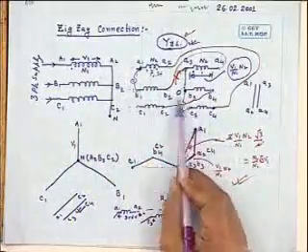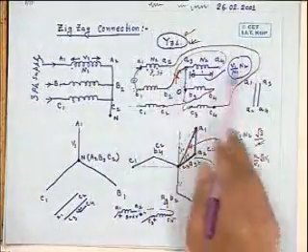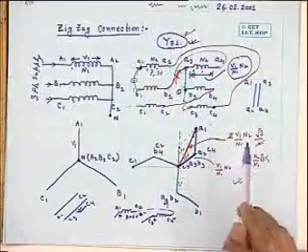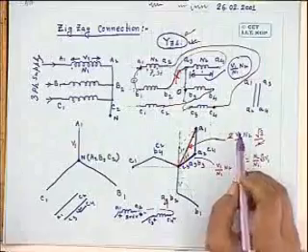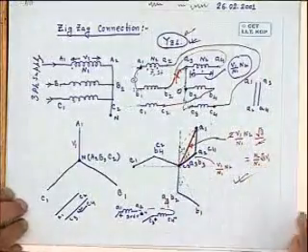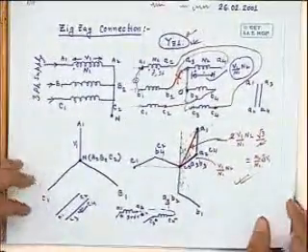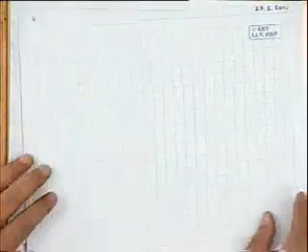And if you look at the direction of the currents also, it will nicely match because of the polarity reversals of series connection. A2 is connected with A4. This you verify. This third harmonic single phase loading is also possible.